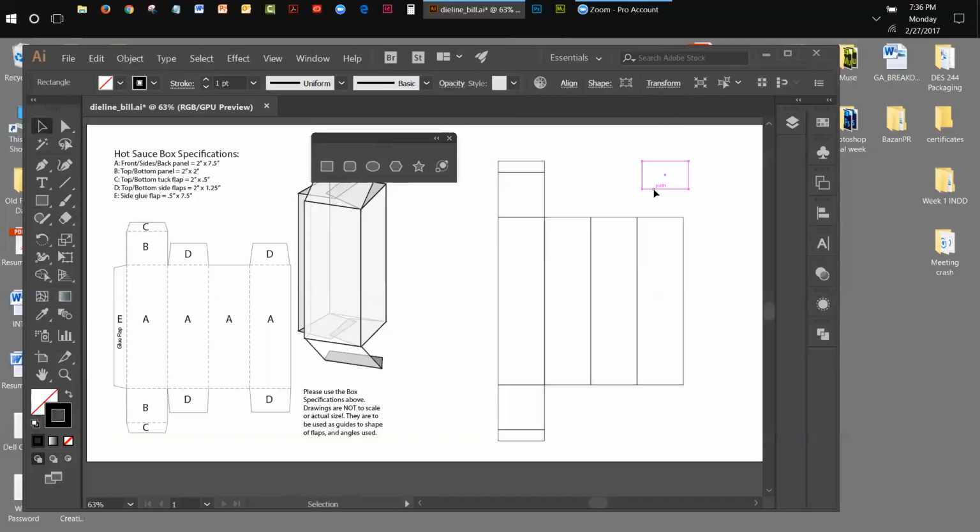Okay, so now I'm going to just grab that guy and I'm going to bring him over until it locks in right there. And again, it intersects. Look for the intersection. And look, these are smart guides. Look for the smart guides to intersect it and to center it along the vertical axis with the center panel beneath it. I'm going to, again, hold down the Alt key, click on it, and I'm going to drag it down until it intersects and locks into place at the bottom, okay?